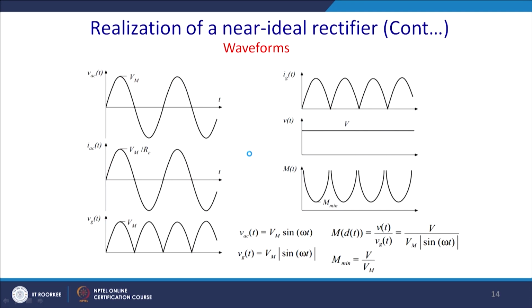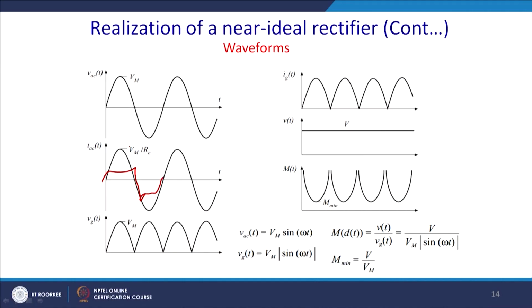So, you have PSE that will be required to be basically a sinusoidal one, but you know how the voltage looks like in case of a diode based rectifier, at the input of the diode based rectifier. So, instead of this kind of thing, we want this to be pure sinusoidal. For this is what we require to do, since we have no capacitor. If you put a capacitor, then current will be peaky and corrupted with a lot of harmonics. So, Vg is this, since you have not put any capacitor,